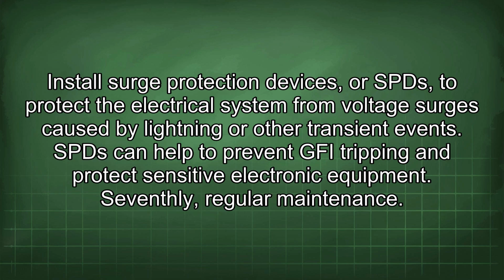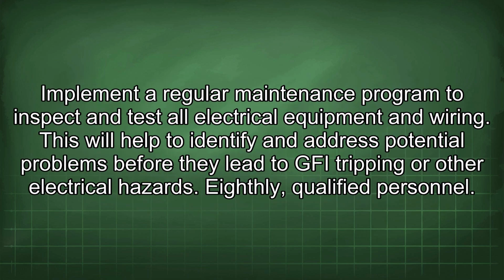Seventhly, regular maintenance. Implement a regular maintenance program to inspect and test all electrical equipment and wiring. This will help to identify and address potential problems before they lead to GFI tripping or other electrical hazards.